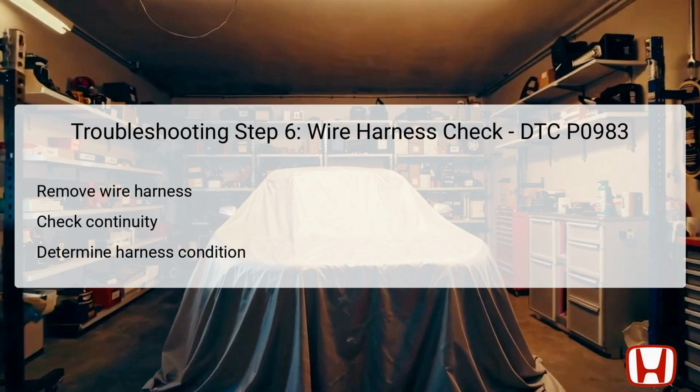If continuity is detected, this confirms that the wire harness is functioning properly, and the next step would involve replacing the Shift Solenoid Valve D if applicable. Conversely, should continuity not be found, this indicates a problem within the wire harness itself, necessitating its replacement to restore proper function in the solenoid and overall transmission operation.